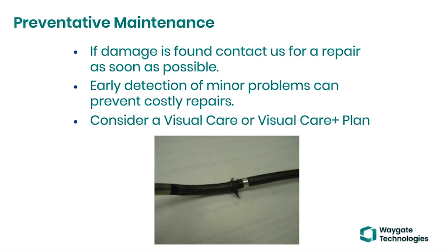Or I've seen people feed the camera in around 1 or 2 stages in a compressor section. The edges of the blade are very sharp, and they just shove it in and out. And if you listen to it, you're going to hear it grinding. Versus gently rotating it back and forth, wiggling it in, and letting the crosshatch of the braid walk you in there. So you can cause premature wear by not paying attention to how you're pushing the camera across sharp sections.